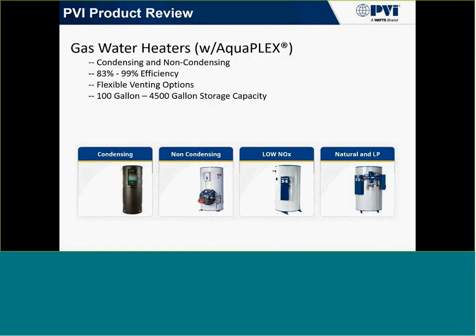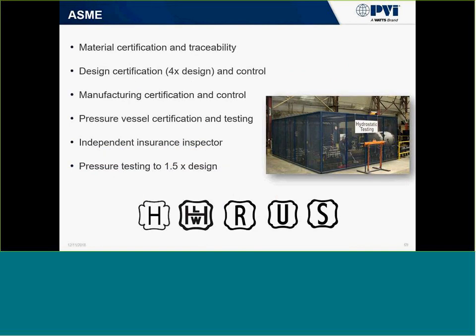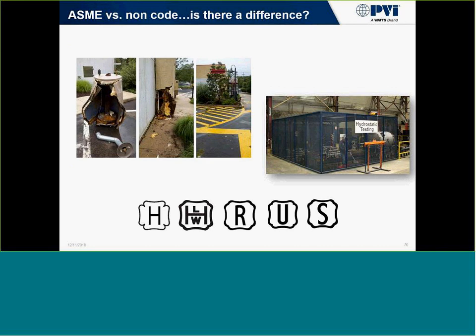So going over a gas water heater offering with PVI, we do have condensing, non-condensing, natural and LP, and also low NOx units. Like we said before, everything's made out of ASME construction. You know, we pressure test at 1.5 times design, and this is why you do it.